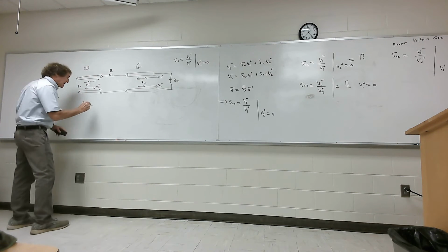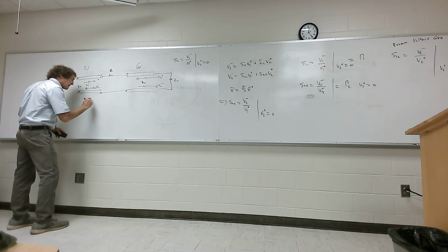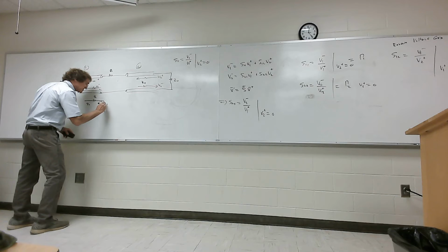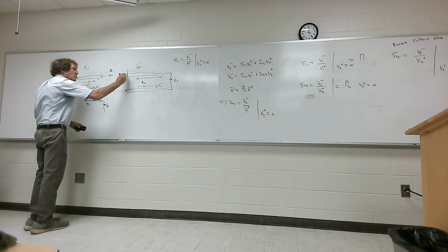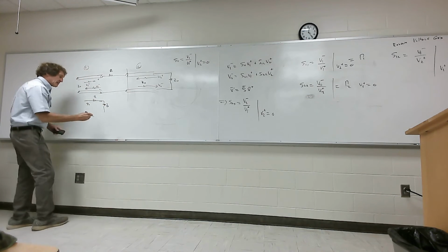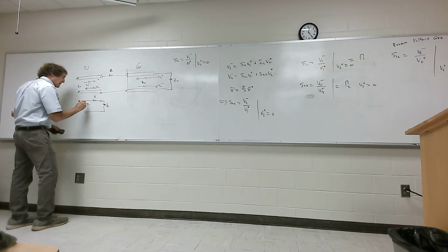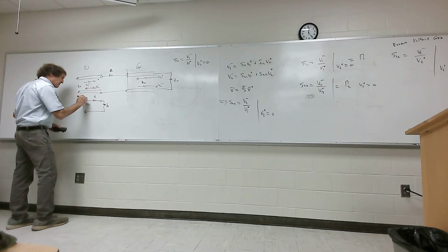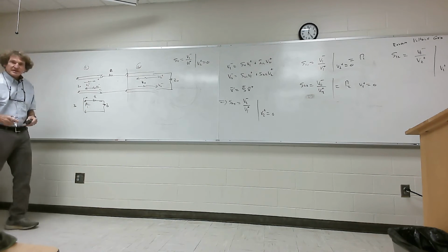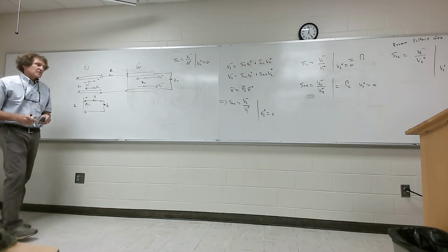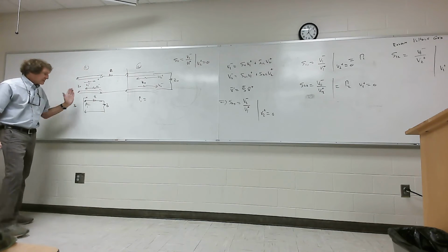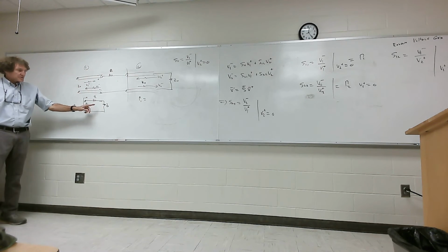Here's the reduced circuit. I have Z0 over here, then I have a resistor R, and then I have another Z0 here. That's this port value right there. It's just Z0. And it comes back here, and I want to find out what the reflection coefficient is right here. So Z0 would be over here. And I want the reflection coefficient of port 1. How would you get that? What is reflection coefficient in a nutshell? It's the impedance you're going into, correct? The impedance I'm going into is R plus Z0.